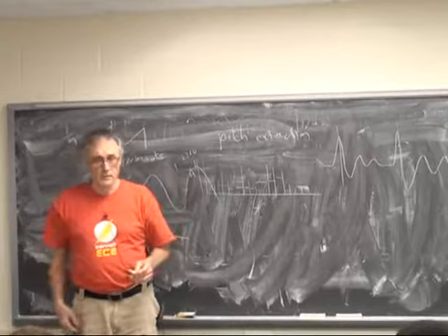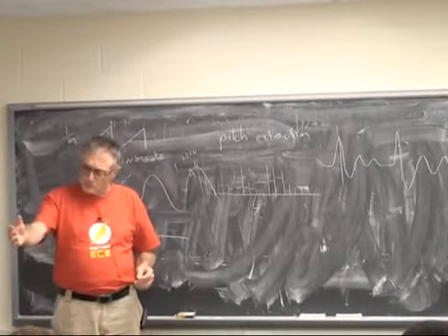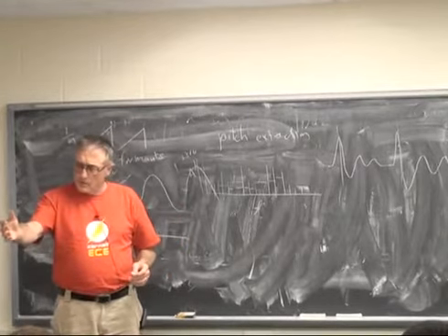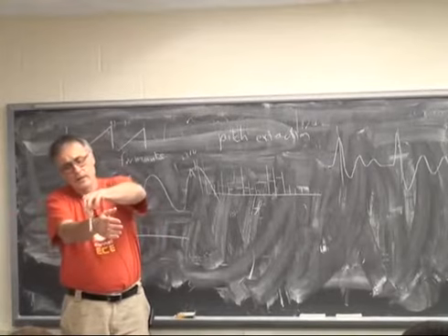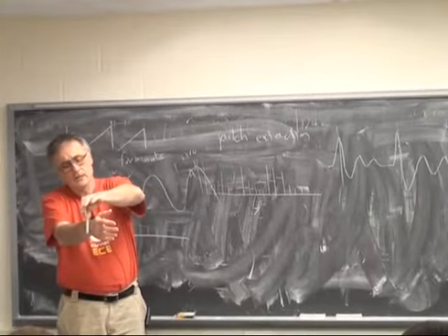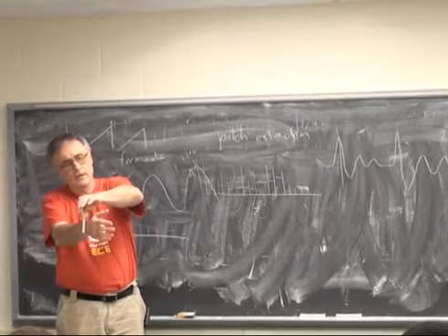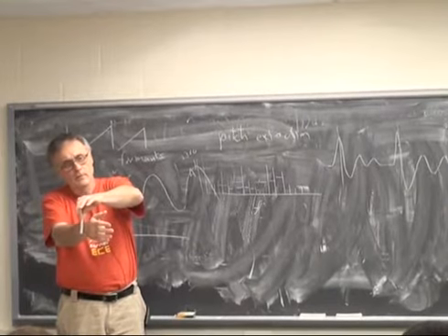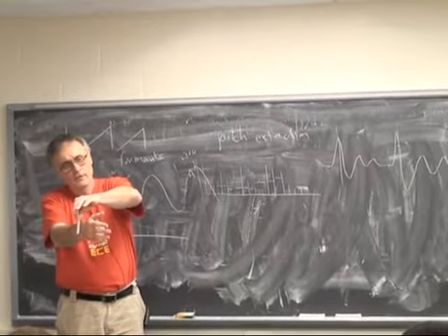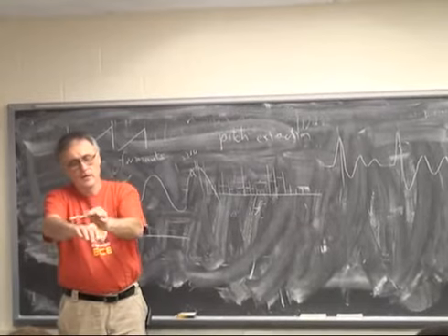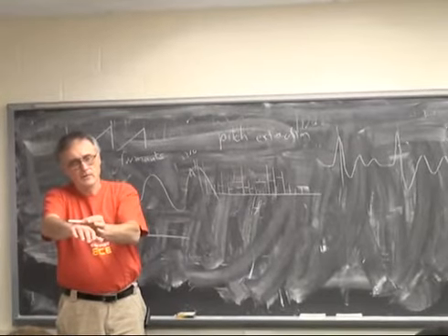If you have a transient motion, you can expect to double integrate the acceleration over time and get an approximation of how much the position has changed. But while you hold your hand still, the apparent position is going to drift because of integration errors in the accelerometer. Also, if you have an accelerometer axis pointing down, your hand is accelerating at -1 g all the time because we're in a gravitational field. You turn your hand this way, the acceleration along that axis is now 0.